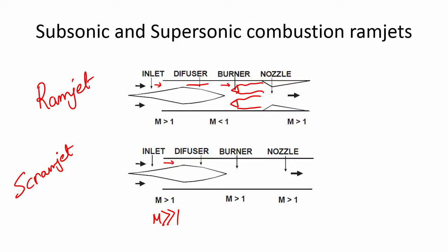Okay. So it is compressed, and then it again passes through the diffuser. A series of oblique shock trains is formed, of course, and the pressure rises as the flow passes through these shock trains and through this convergent cross section.